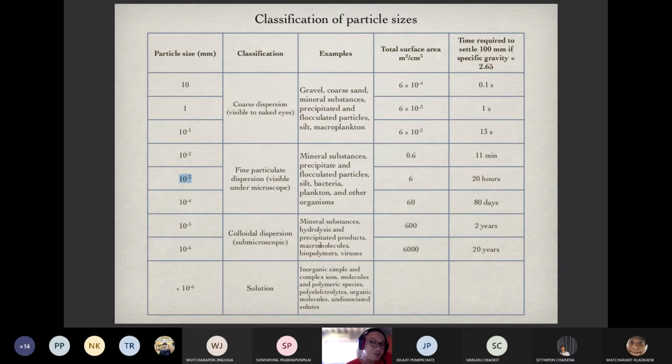The fine particles cannot be precipitated. They remain suspended, so it gives a certain turbidity. If you measure the turbidity, it will be something like 20 to 30 anyway. So it may not be removed even if you leave it for days.